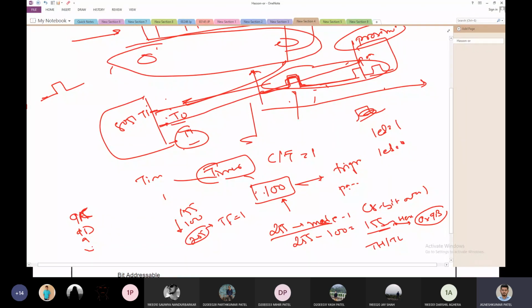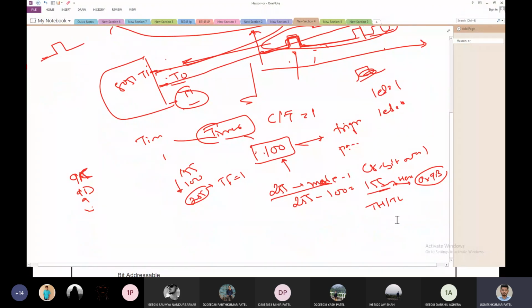Now what I have to do is send a signal to the packaging machine. So this is the concept of the program. Now we are going to write a program, but before writing it, let's understand the content of the various registers. What should we write in TMOD and TCON? TMOD is basically your gate, your C/T bar, your M1 and M0, and the same thing is repeated over here. But this part is for timer 0, so I'm not writing it, but I'm interested here.